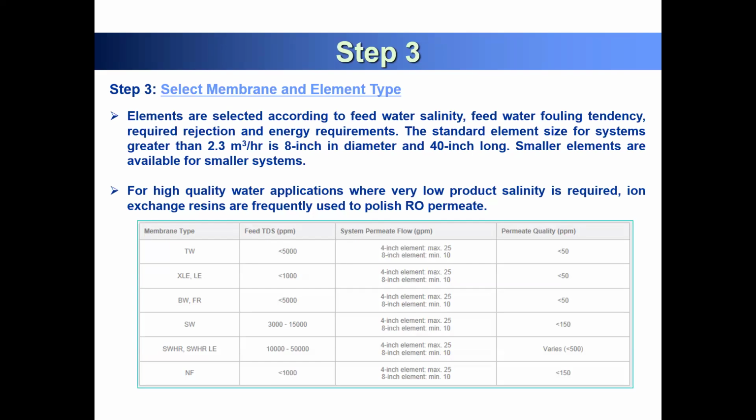You can download from other companies, specifically if you are interested in their membrane elements. They have similar functions to this Dow FilmTec software. So you can select other companies' membrane elements, or this Dow FilmTec membrane would be a good starting point to decide.